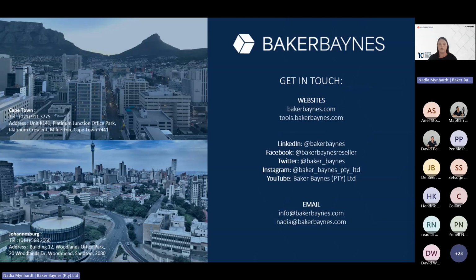But Pranal, if you have a specific column in Revit that you want to use within your Infraworks model, just share it with me and I will see what we can do within the infrastructure parts editor for you. But at the moment, I know that Revit families don't integrate well with Infraworks. You can only take a full Revit model to Infraworks. I hope that makes sense.